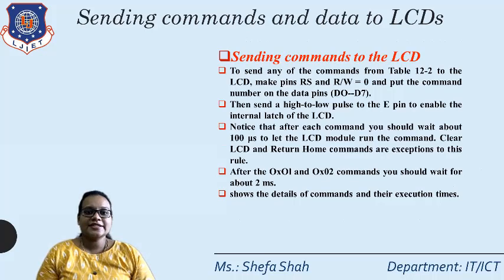Then second step, that is sending commands to the LCD. So to send any of the commands from the table to the LCD, make RS and RW equal to 0.